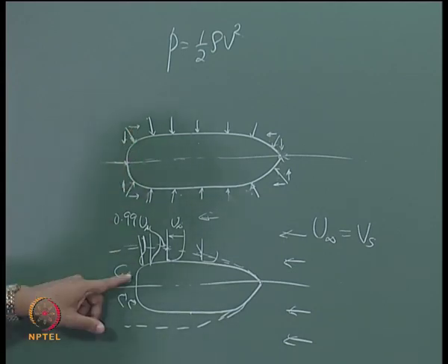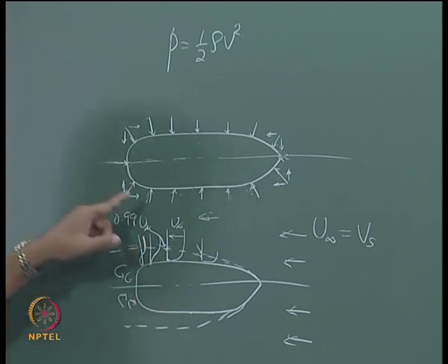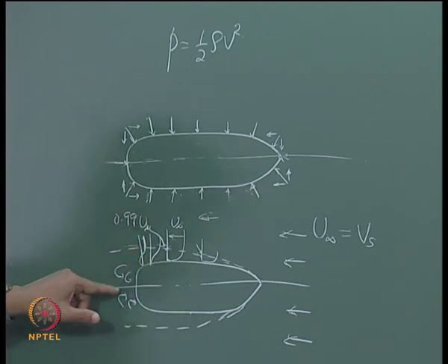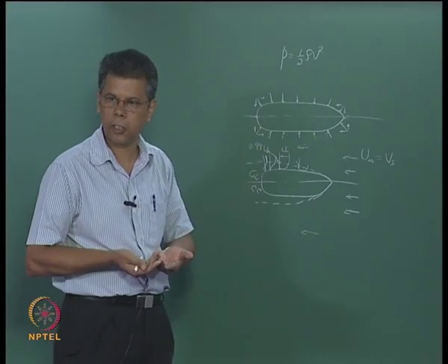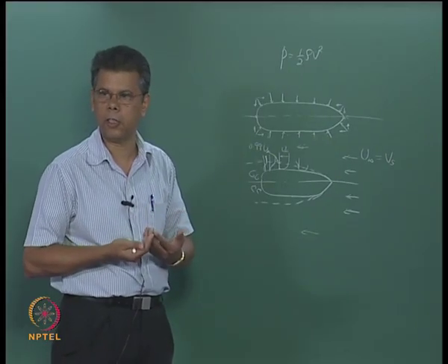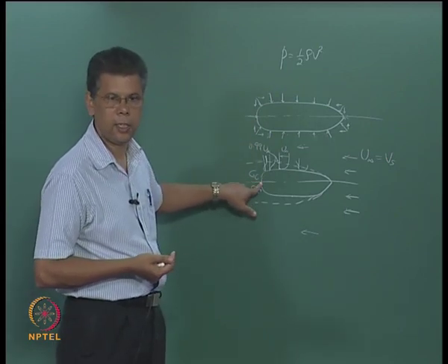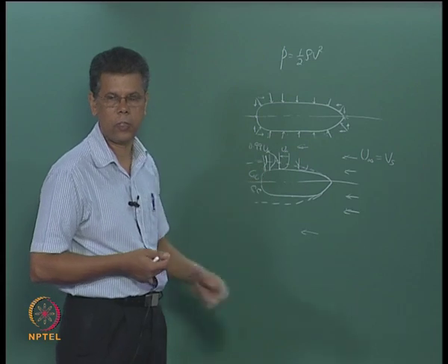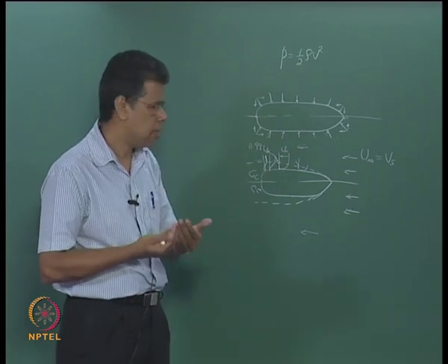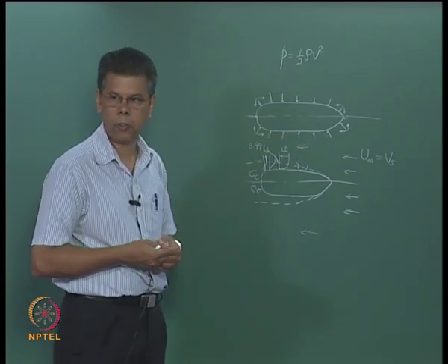Now you consider this case where you consider the boundary layer, viscous fluid, there is a flow separation, and the velocity of flow is not 0, it is a non-zero quantity. So what happens to pressure compared to these two? The pressure here will be less because the fluid has attained a velocity due to the flow separation.